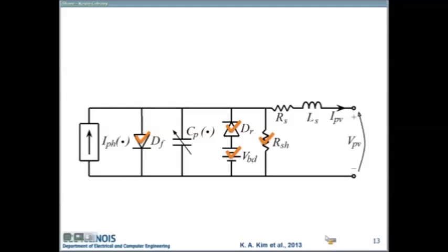Okay. So next, we want to look at these AC characteristics. So let's look at the shunt resistance, series resistance and inductance. So how do we actually find these values? And note the inductance tends to be relatively small. You have really small leads, so you're not really going to have a very large inductance here, and it's only going to come through at higher frequencies.